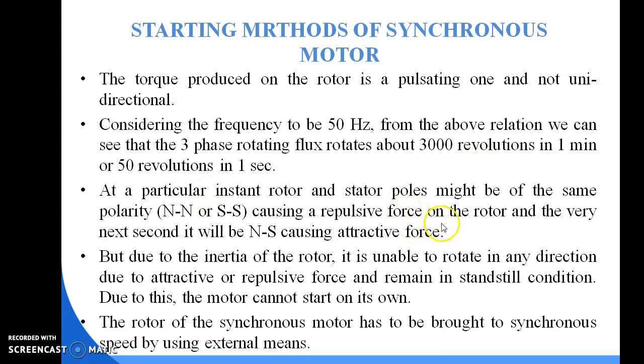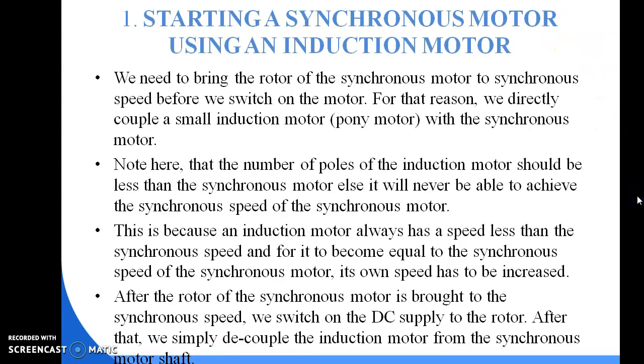A repulsive force on the rotor, and the very next second it will be north-south, causing an attractive force. But due to the inertia of the rotor, it is unable to rotate in any direction due to attractive or repulsive forces and remains in standstill condition. Due to this, the motor cannot start on its own. The rotor of the synchronous motor has to be brought to synchronous speed by using external means.